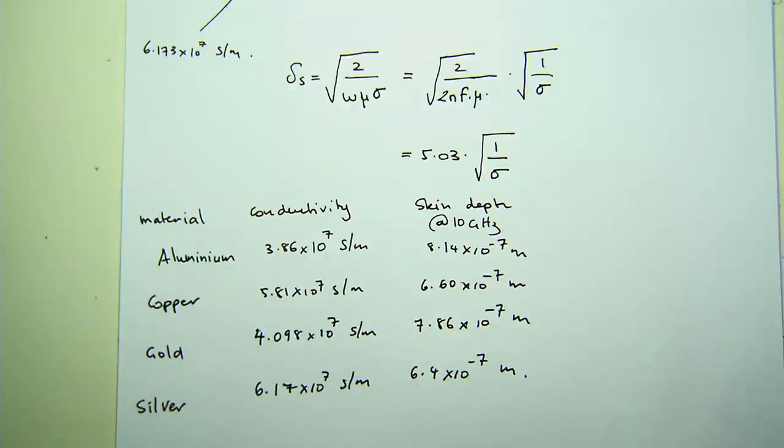If you're at low frequencies where your skin depth is large, what it means is you need to get real pieces of metal, cut it, and go to the metal workshop. And for people like me that are electrical engineers, going into a mechanical workshop usually means cut fingers, so try to avoid those things. But if you're at 10, 20, 60 gigahertz, if you want to build a nice waveguide or a horn antenna, well, go 3D print it.